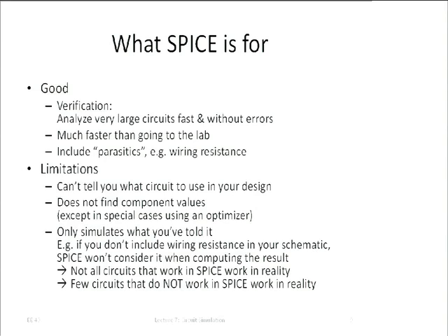So all of that said, right, SPICE is really great and it's extremely useful. We absolutely need it. I argued already today, nobody makes a chip without using one or the other version of this program. But it does have limitations. So already mentioned, right, a circuit simulator cannot tell you what circuit you should use in order to realize a certain function. You need to know that. And how do you know that? Well, we'll look at lots of circuits and we'll work with them in 4D, and over the years you collect more ideas on how to do things.